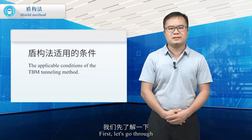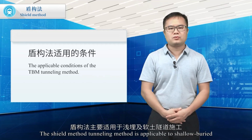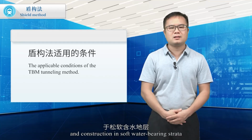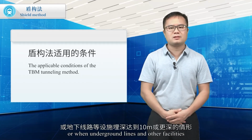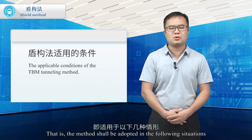First, let's go through the applicable conditions of the TBM tunneling method. The TBM tunneling method is applicable to shallow buried and soft soil tunnel construction, and construction in soft water-bearing strata, or when underground lines and other facilities have a buried depth of 10 m or more. That is, the method shall be adopted in the following situations.